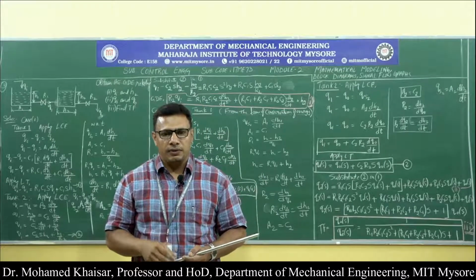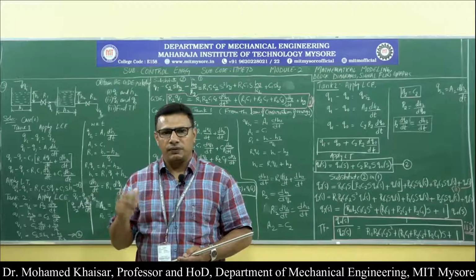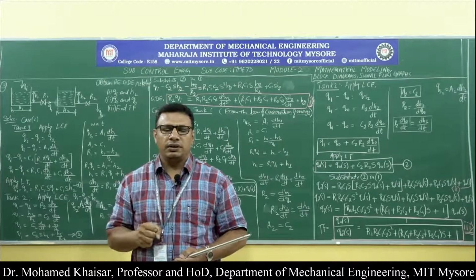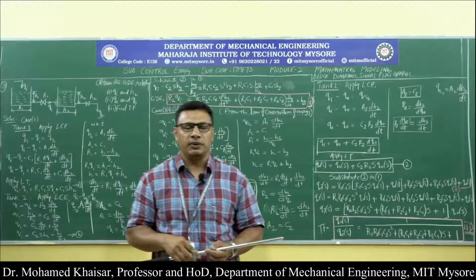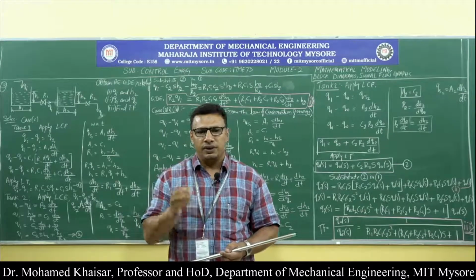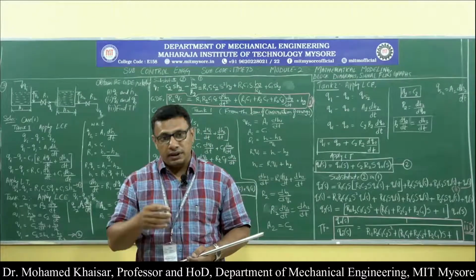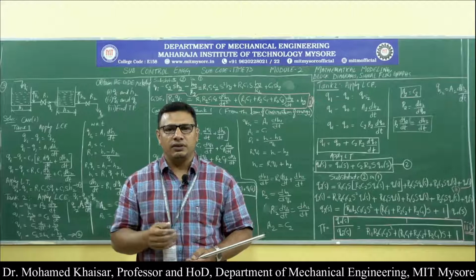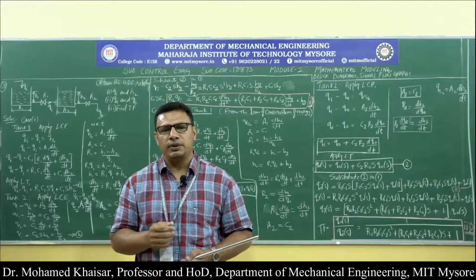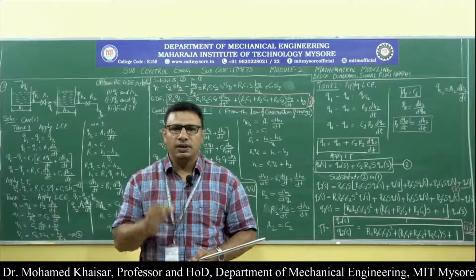And one more time, network approach is a wonderful improvisation in the process of problem solving, because by virtue of it being easy to analyze electrical networks, the terminologies that have been used in electrical networks or electrical systems have been adopted over here in various other systems such as hydraulic systems, liquid level systems, pneumatic systems or thermal systems. Thereby it has made it a lot easier to solve the problems and arrive at the basic requirement of this particular module, that is the mathematical model, that is nothing but the transfer function.